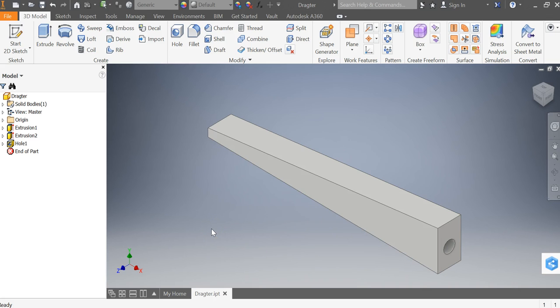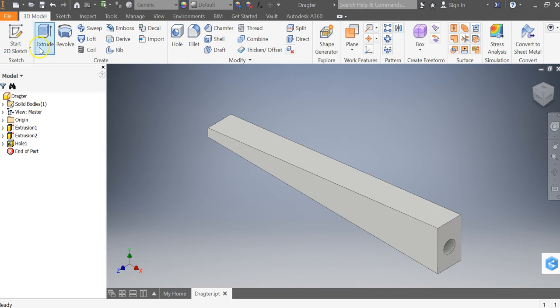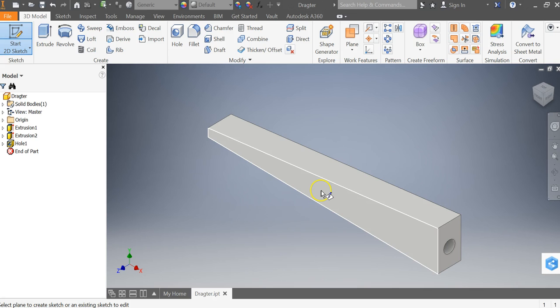So here, the location of your holes, horizontally speaking, will have to agree with your own design. The height of the center of these axle holes is going to be exactly 0.156 inches. I am going to show you how to create the holes 1 inch from the front and 3/4 of an inch from the back. But the location of your holes will vary depending on your designs. Just make sure that for the front axle it is nothing less than 1 inch, and for the back one nothing less than 3/4.